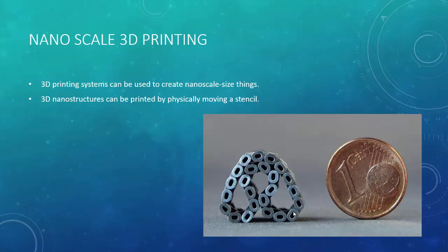Programmable height nanostructures, which are thin, have been made by metallic physical vapor deposition through a piezoactuator controlled stencil mask having a single nanopore in a silicon nitride layer. This metal vapor technique is moreover advantageous because it can be used on surfaces that are so sticky, so tricky, that it would be unthinkable for high temperature chemicals for ordinary lithography to be used on.